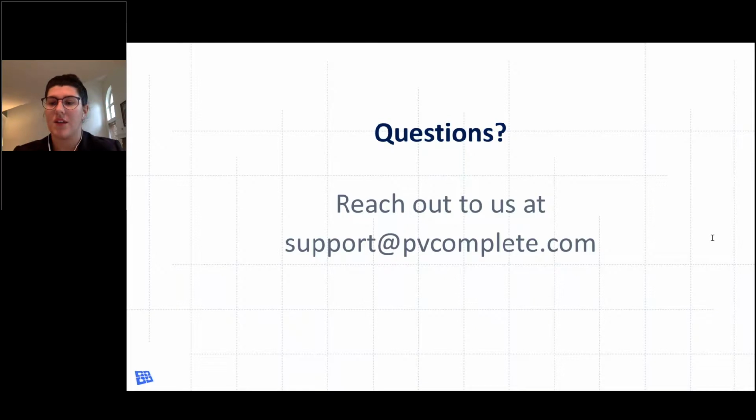Question 5. Does CASIS consider the losses due to shadows between racking structures when reducing the pitch? Yes, it does. And again, a reason we love CASIS is because it very, very closely mimics outputs you would see from PVSyst. There's a lot of nuanced inputs that you can consider within CASIS.